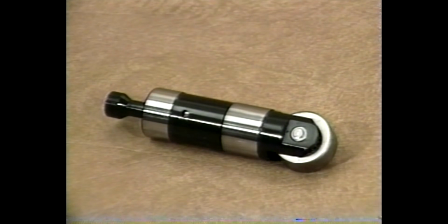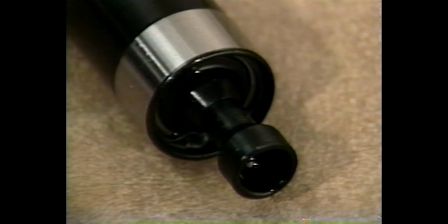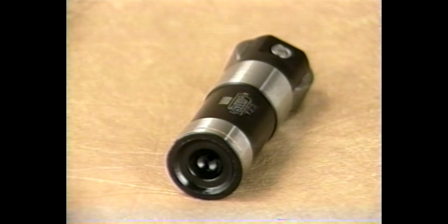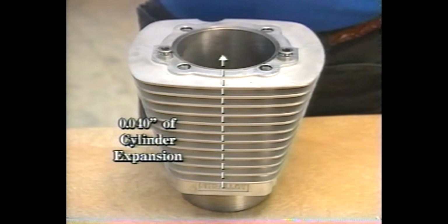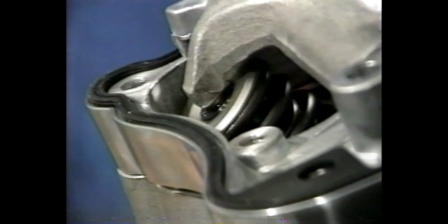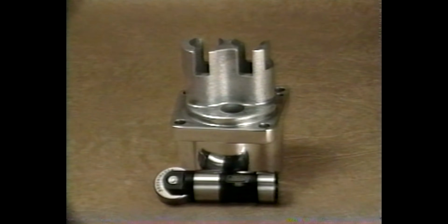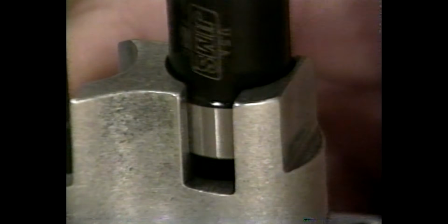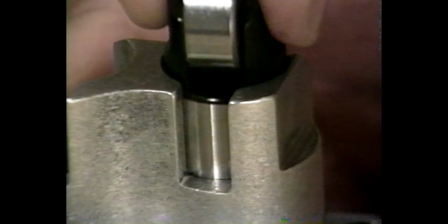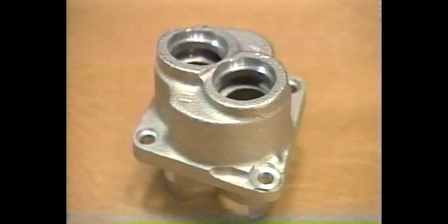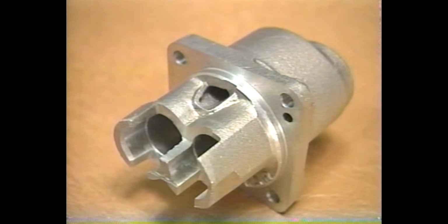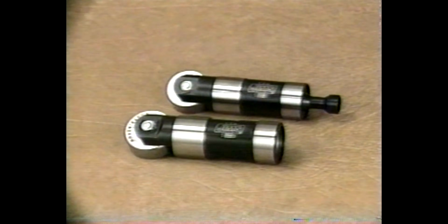GIMS claim that their Power Glide kits will eliminate the shock absorber effect of stock hydraulic lifters and simulate the performance of solid lifters. They also have the added advantage of being able to compensate for up to 40 thousandths of cylinder expansion, thus maintaining a zero valve backlash clearance to the highest RPM a Harley engine can safely turn. Power Glide hydraulic lifters are what we use when we are hand matching hydraulic components to a running fit of 2/10,000ths of an inch. Another benefit of the Power Glide hydraulic lifters is that they will also perform in stock tappet blocks and do not require special tappet blocks until the lifts of our cam passes 550 thousandths.